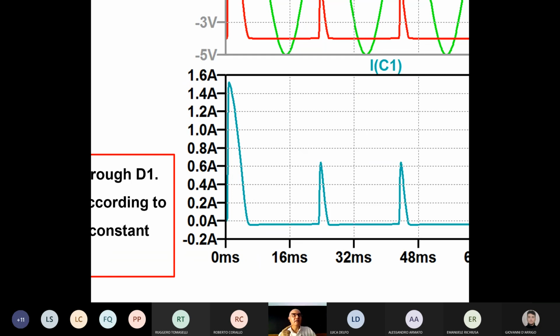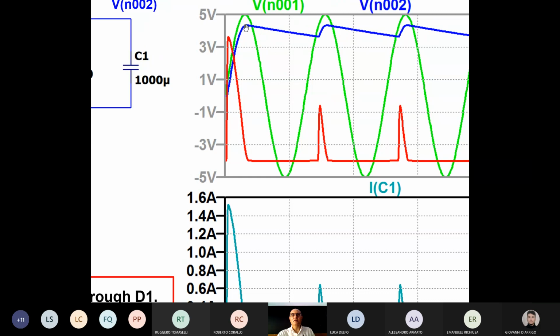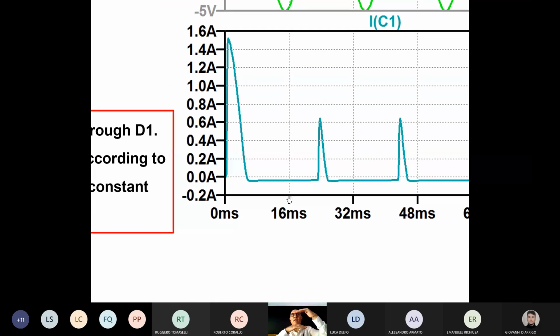It's a negative current, meaning that it's a current coming out of the capacitor, because usually in the plots, the current going into the capacitor is positive, and the current going out is negative. Also, this current is almost constant. Why? Because the voltage across the capacitor is almost constant. There is a very small variation. It's a small variation, but in this scale, which is very compressed, you can almost see the difference. You see that there is only a very small reduction in the current here.